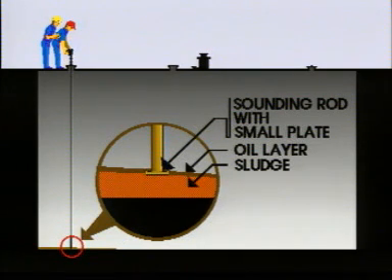In this vessel there are only vapour control valves in the aft end of the tanks. If there is a discussion about ROB and the dip clearly indicates liquid, use the wedge formula or wedge table to calculate remaining cargo. If the dip indicates sludge or sediment, you should also suggest using the wedge formula to compute ROB.